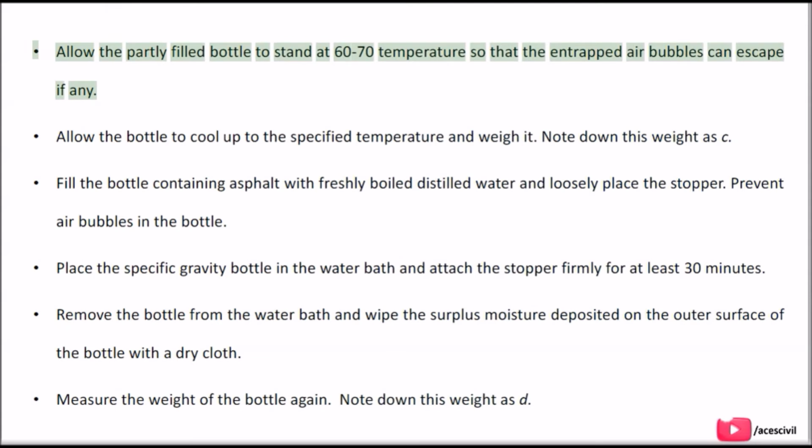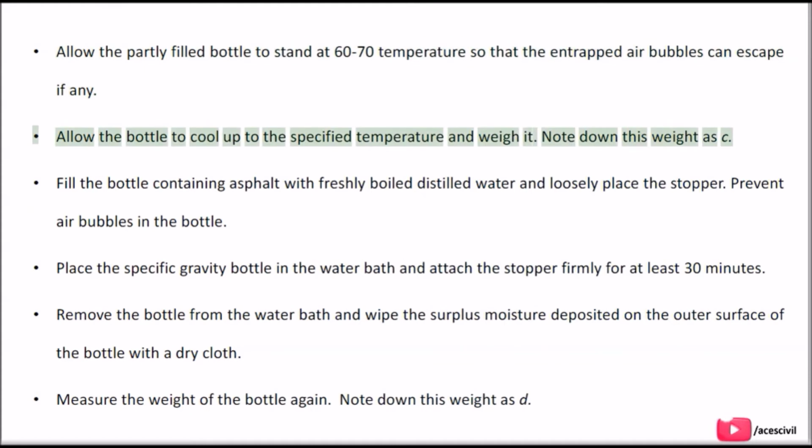Allow the partly filled bottle to stand at 60 to 70 degrees temperature so that the entrapped air bubbles can escape, if any. Allow the bottle to cool up to the specified temperature and weigh it. Note down this weight as C.